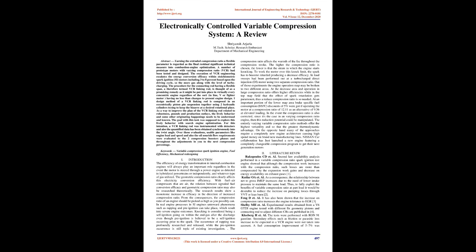With fuel-air cycles that are air based, the relation between indicated fuel conversion efficiency and geometric compression ratio can also be researched theoretically. The research results show a monotonic increase in efficiency with increased compression ratio. From the results, the compression ratio of an engine should be chosen as high as possible.